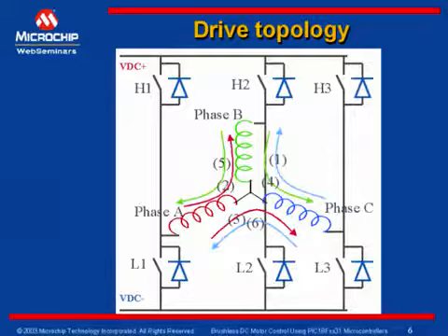A brushless DC motor has windings on the stator and alternate permanent magnets on the rotor. Brushless DC motors are electronically commutated based on the rotor position with respect to the stator windings. This means to run a brushless DC motor, an electronic drive is required.